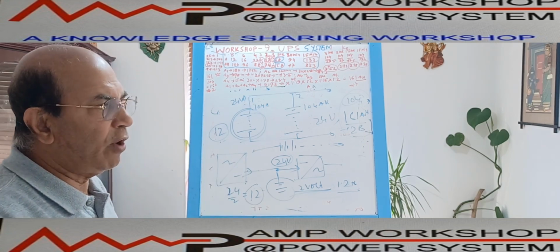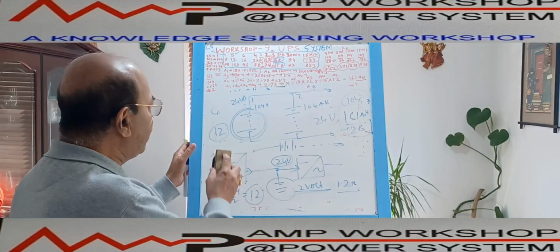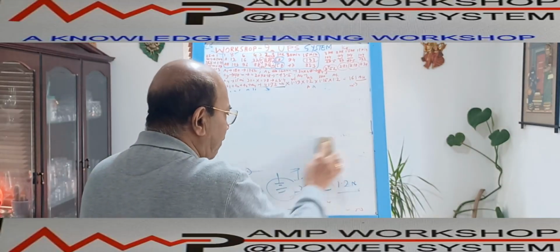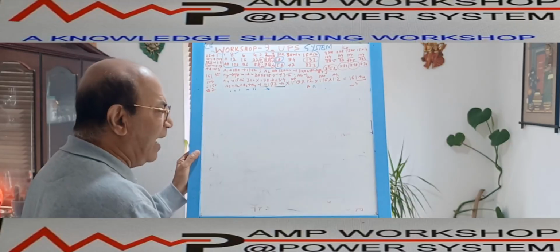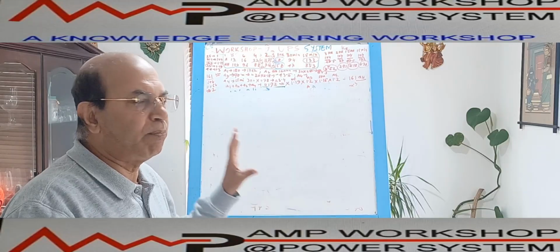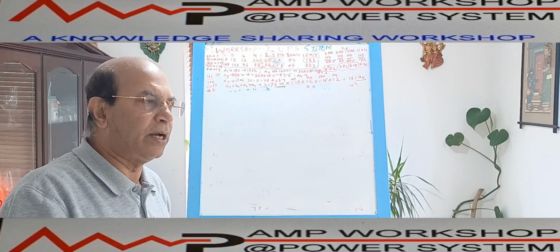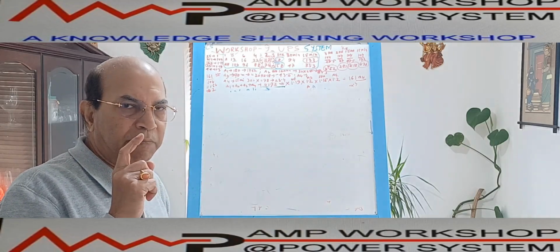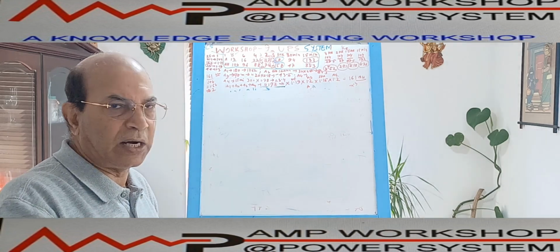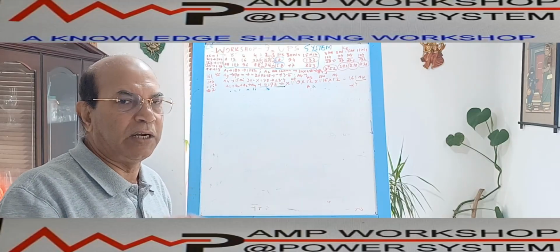From the curve, for each section we have to calculate the change of current. Then for each section, starting from the start of that section up to the end of the battery discharge, you have to calculate the duration. Keep in mind, I am repeating this because you should not make a mistake here. To decide the total time for that particular section in deciding the K factor, you have to calculate the total duration from each section's start to the end of the battery discharge.